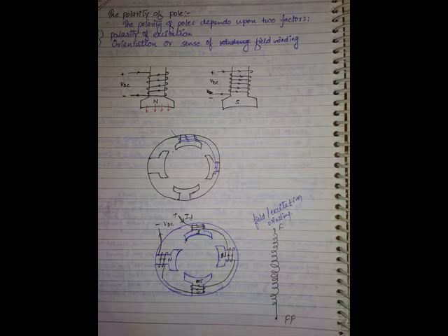When there is flux and the conductor cuts the flux, EMF is induced in it. Similarly, when there is main flux and armature flux, they interact with each other and the armature is subjected to a force, so it rotates. Finally, what I want to convey is that in this energy conversion process, anything to anything, there is a coupling medium inside, which is nothing but the magnetic field flux.